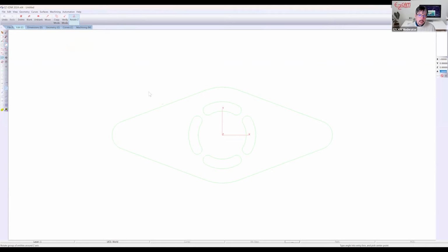All right, now let's get into programming. But before we do, we have to create a path, and we call that a curve. So we go with New Curve. When you're in curve chain, you can double click, and all the connected geometry will form a closed curve. And every curve has to have a start and end.